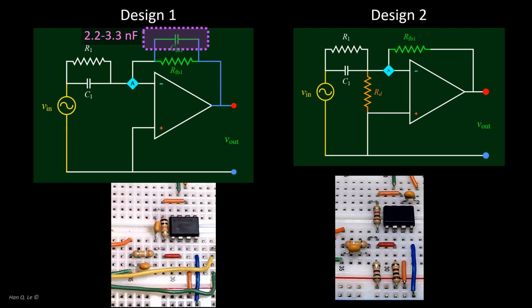It is to dampen the resonance oscillation for abrupt or step output in response to an input slope discontinuity. The capacitance value matches to the LM741 op-amp bandwidth and the design feedback resistance. A more detailed discussion is given in the appendix.